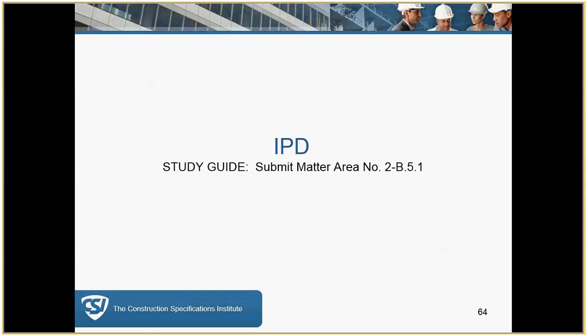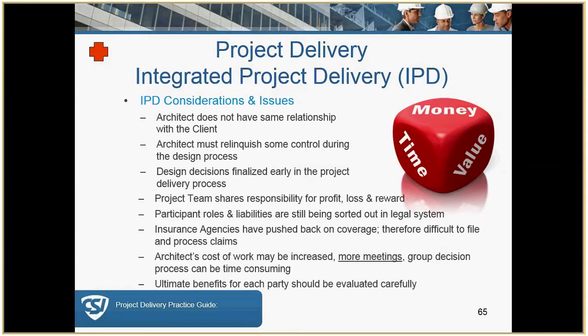IPD, there's an AIA document that you will want to reference. It's actually available as a PDF free online. Integrated project delivery did start in California. It is a blend of design, build, and teaming. The main thing you want to know here, there is now one contract. Everybody in this project delivery method signs one single contract. And the one contract that I'm familiar with, the project was quite a ways through before all the attorneys agreed on the contract. But again, this is something that you want to go through.